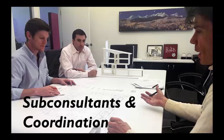Now sometimes they can do this with the help of some digital software where they can take models and drawings and put them together and see if there are clashes, or what we call clash detection. But most of it has to do with the architect being aware enough of every facet of the project where they can look at different things and say, this beam is in the same location as this piece of ductwork that the mechanical engineer has. So we need to coordinate that, meaning we need to talk to both of them and see if one or both of these things can move so that they're not in conflict. And it's really the architect's job to do coordination. And it's a huge job.